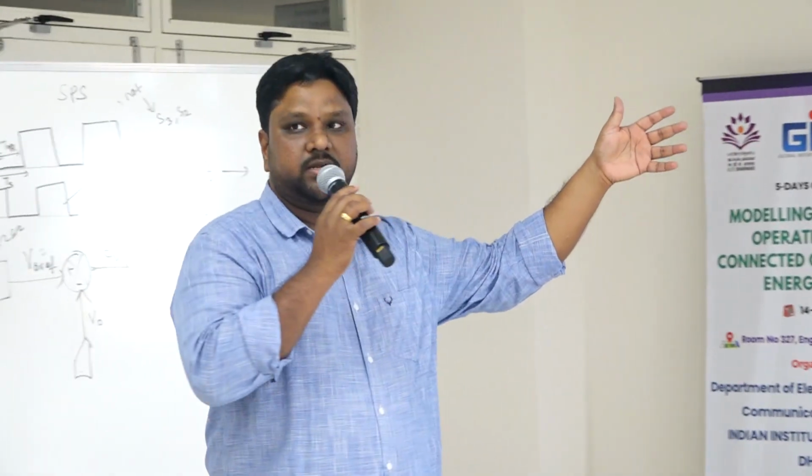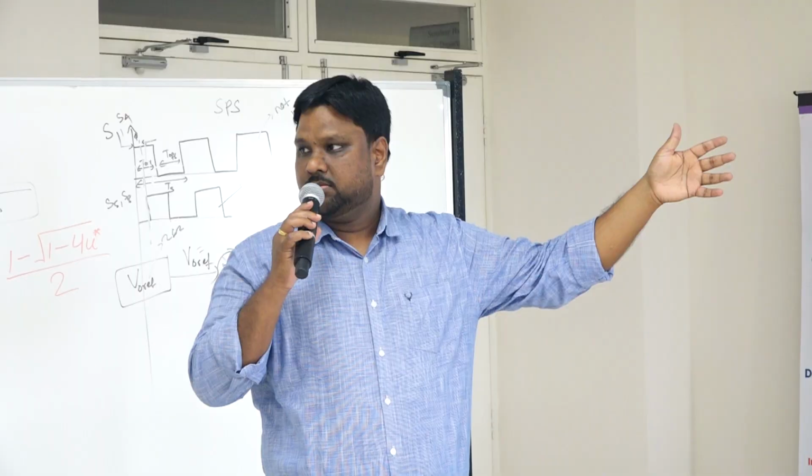Depending upon how much the output voltage changes, it will update that phase shift, and accordingly you get your desired control. Instead of the phase shift I gave myself in the previous example, 30 degrees, now it is through the controller, which makes it a closed loop control. So that generates 4 sets of pulses.